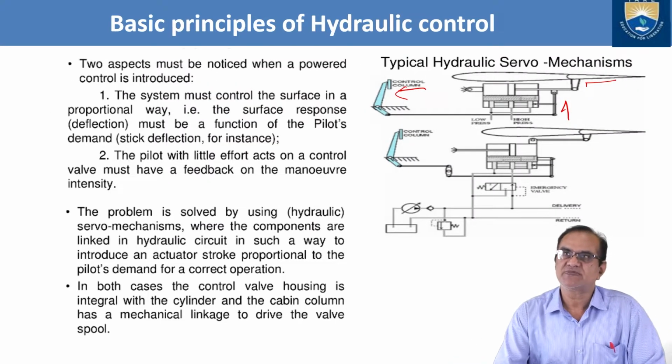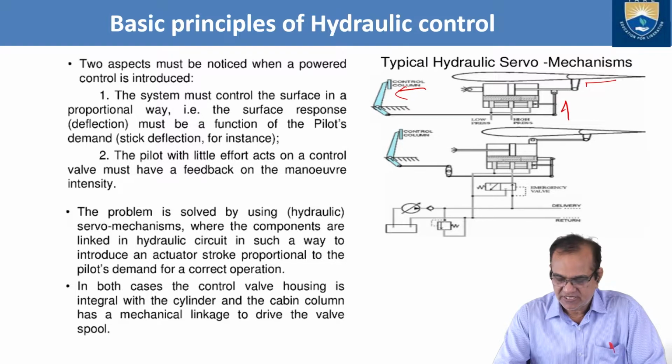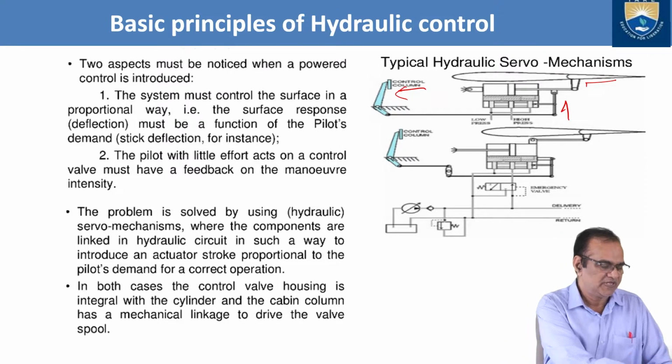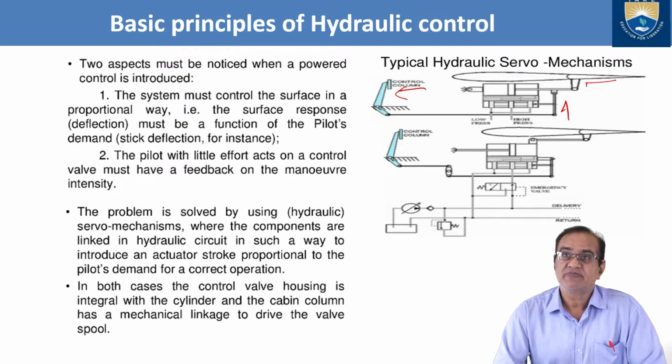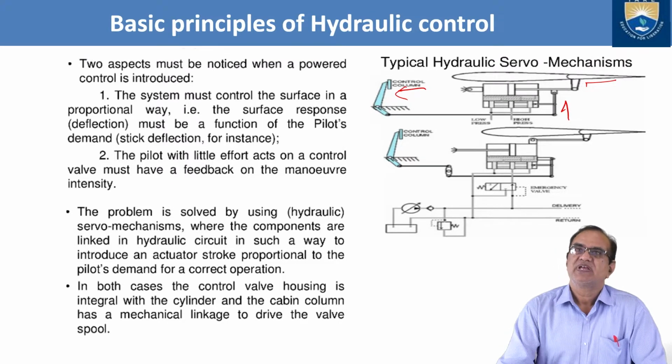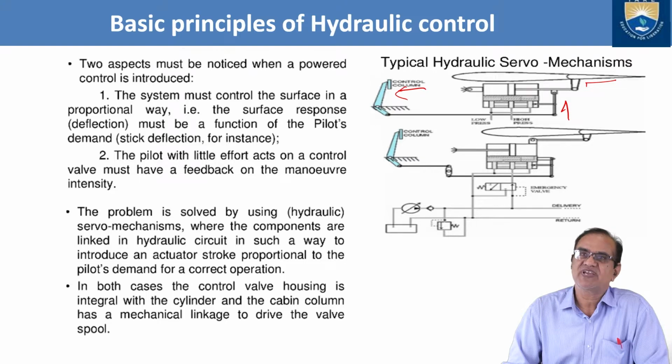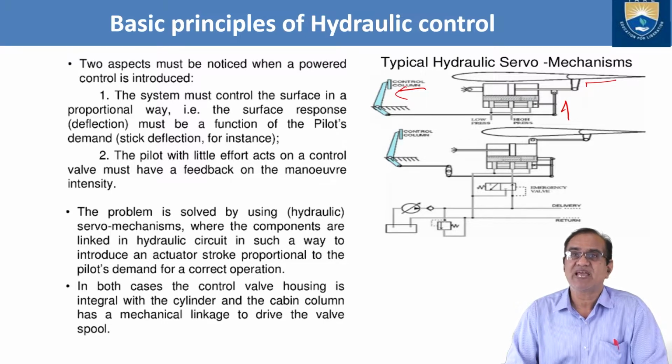In these basic principles of hydraulic control, we can see here that two aspects must be noticed when powered control is introduced. The system must control the surface in a proportional way. That is, the surface response, the deflection, must be a function of the pilot's demand, that is stick deflection, for instance.